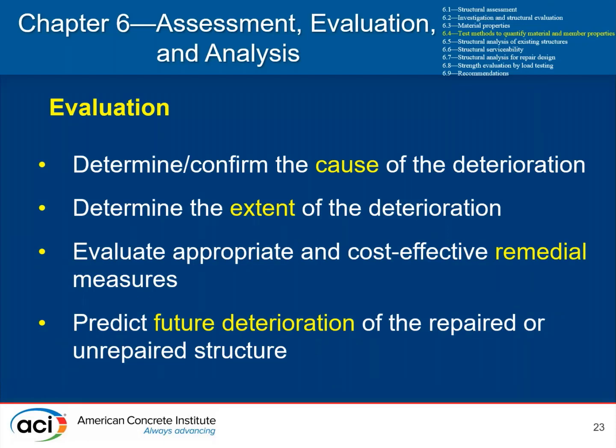So the evaluation process, as part of the assessment, evaluation, and analysis of a structure, is to determine and to confirm the cause of deterioration. We know that there's a variety of conditions and situations that can precipitate deterioration in concrete. Of course, the one that a lot of people think about is reinforcing steel corrosion. There's also other deterioration processes: freezing and thawing distress, alkali silica reactivity, delayed ettringite formation, etc.